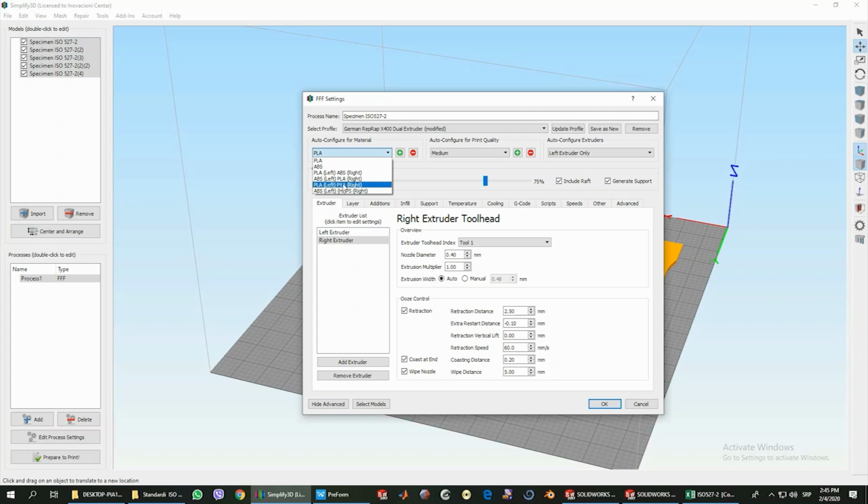With PLA material, PVA can dissolve in water. So you print with 2 materials using PVA for support, maybe, or not, and just place the model in the water or limonene, and the PVA or HIPS will dissolve, leaving only PLA and ABS.